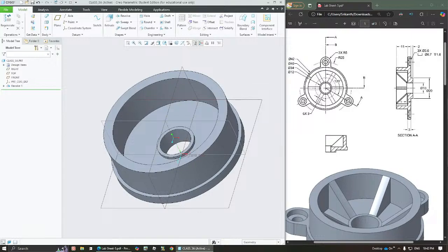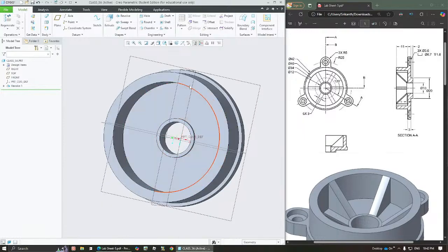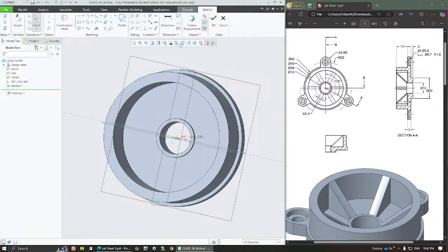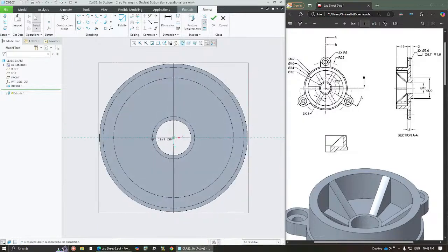Next thing that we need to do is to create this particular thing. So for that, let's choose this place, go for extrude, and then orient it properly. Next, I'll choose a rectangle. First endpoint, I'll click on this arc. The second one, I just need to constrain so that it falls on the other side of that. It should be highlighted with green.